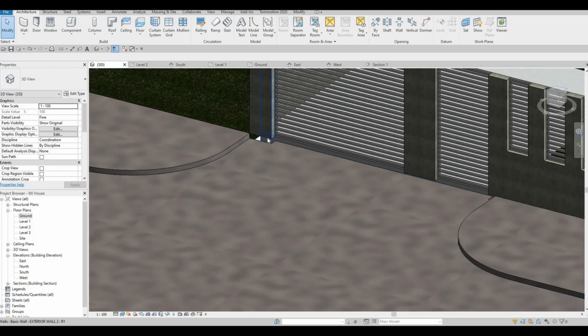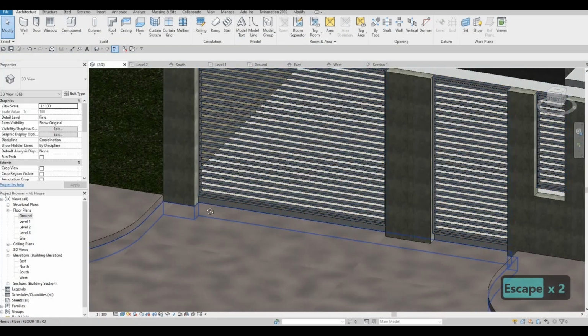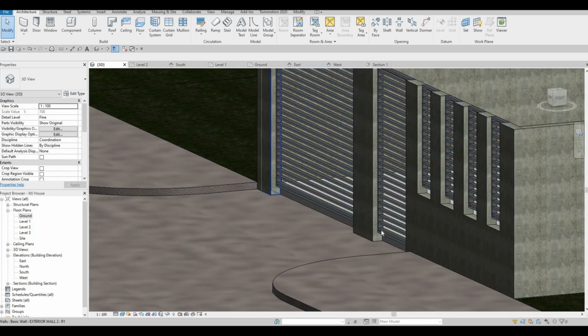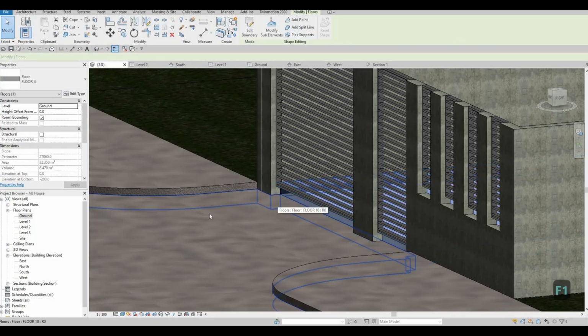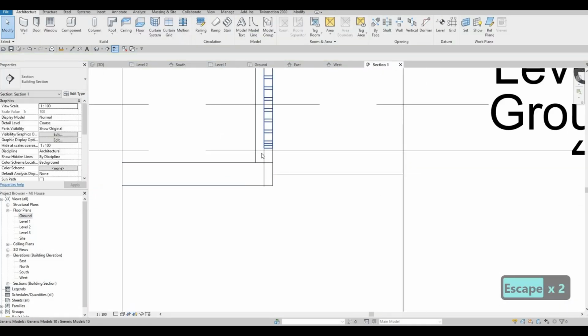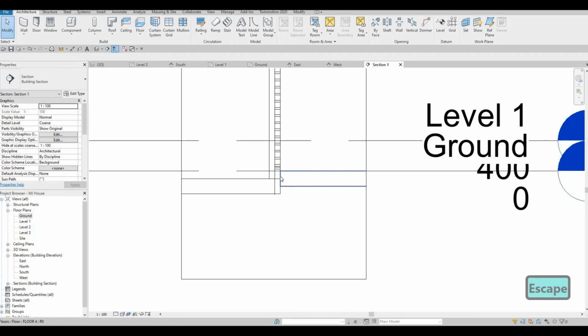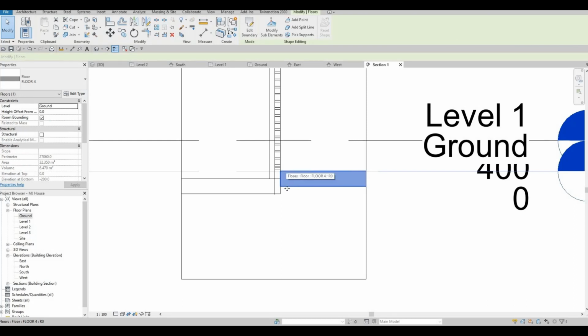And then what we could do is just select this wall right here, pull it down, so negative base offset, -100. So that's good now. We could just add in something right here so that it flows perfectly. So what I'm gonna do is go to the ground. We could double click on this section, and then we have something right here. So from the floor to another floor, we could create an edit from here.